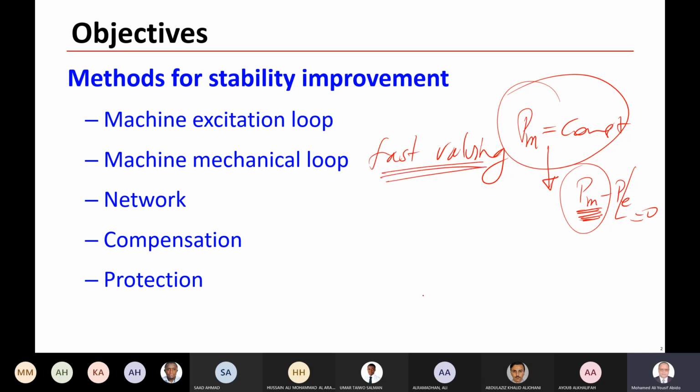In a very short time, you can divert the steam going to the turbine, so you can reduce the turbine power. Of course, this will affect the turbine mechanically, meaning mechanical fatigue of the rotor and so on, due to this fast change of the power.